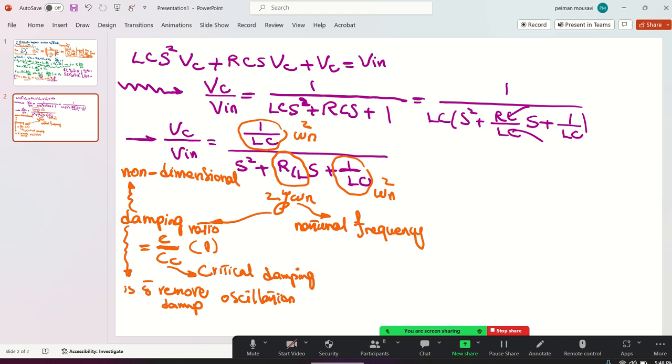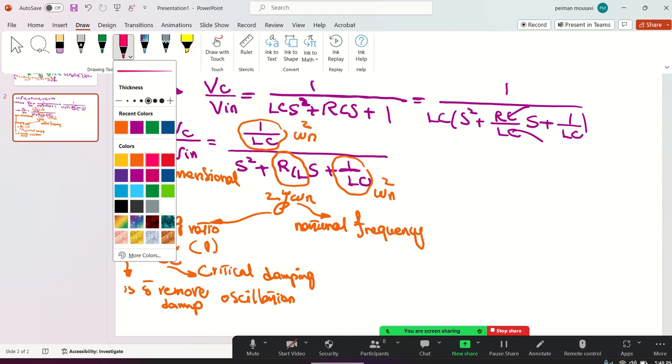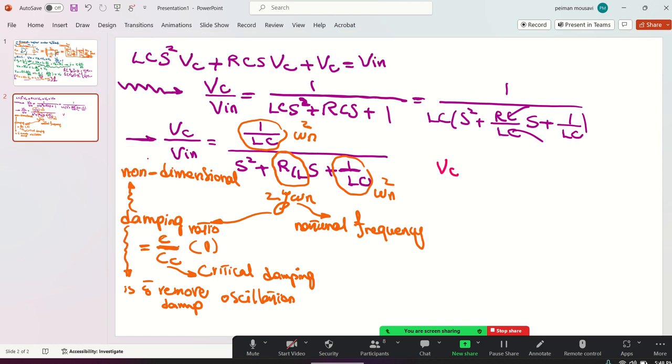When you pass the vibration course, you're gonna go there in detail. So, as I promised you, I can write the second order closed loop transfer function of this RLC circuit as the universal expression with natural frequency, and its unit is radian per second, from dynamics course. Natural frequency means the system oscillates by itself without an excitation force.